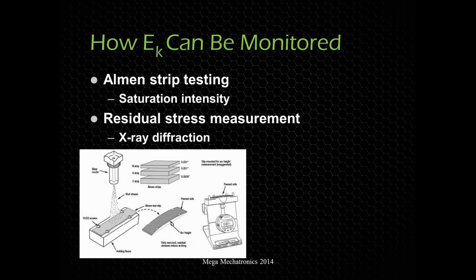In addition to that, you can do residual stress measurements with X-ray diffraction, where you're shooting X-rays and looking at the crystal structure and gauging the residual stresses. In addition, you can mount the part and polish it, so the side profile, and using a precision hardness tester, you measure at certain depths from the edge of the surface of the part. So the more residual stress, the higher hardness it's going to be.